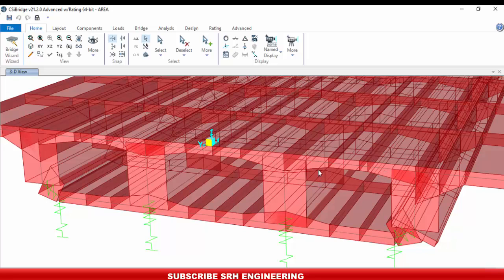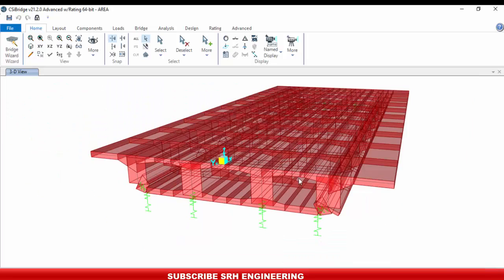If you see this top slab, because this is center line modeling, this is the center line of the web. This extra portion is coming and overlapping with the web thickness. Similarly here, and similarly here. So this much area which overlaps here is contributing more load, more self weight and more bending in the area model, which we need to reduce to get the actual results.